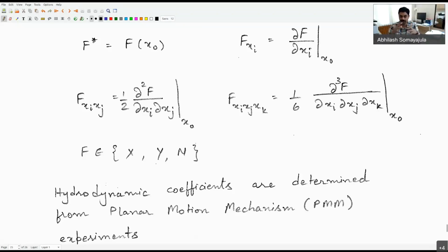But if I don't have them, the hydrodynamic coefficients from one ship to the other might vary more significantly, because they have a stronger dependence on the geometry of the vessel. So in that sense, it's not that one method is immune to experiments. You're right. Both are requiring some amount of data which we may not know. But we may be able to get away with some approximations in one method as compared to the other method we may not be able to get away with.